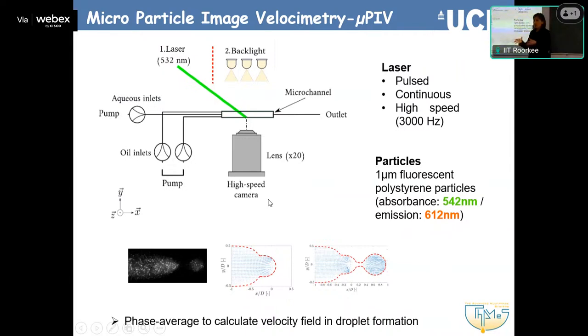The reason is that we have small channels with a lot of material, solids, and interfaces, so if we used the same light, we wouldn't be able to see anything. In a way, we block all these reflections from the walls of the channel, inside, outside, everywhere, by putting in a filter to avoid the green light and only reading the fluorescent light. I should have mentioned it earlier, but it is an important thing in microchannels,